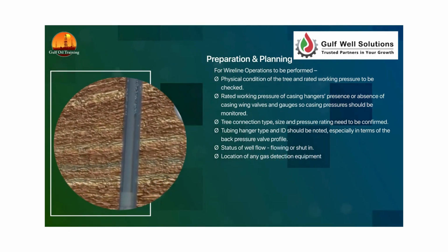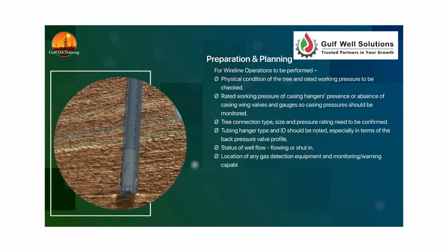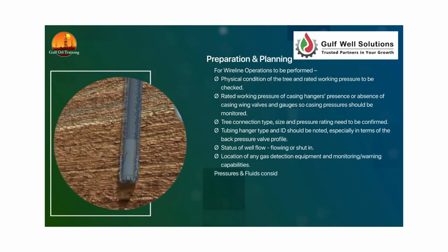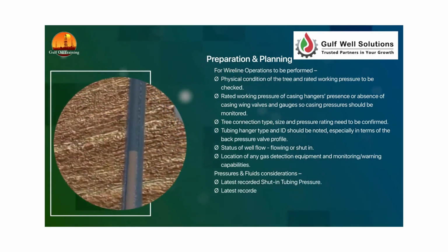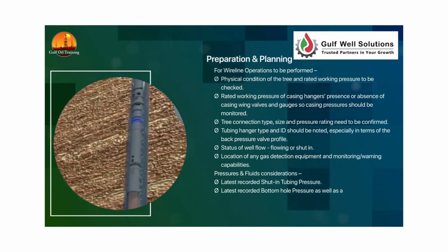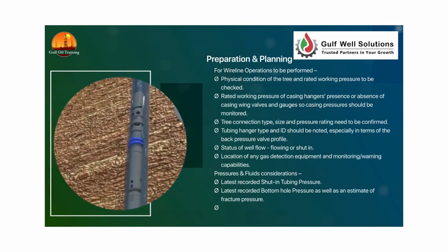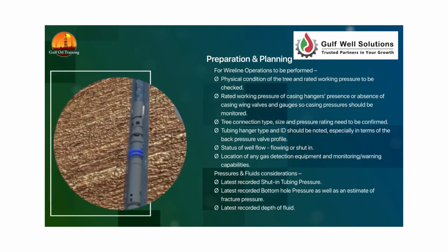Pressures and fluids considerations. Latest recorded shut-in tubing pressure. Latest recorded bottom hole pressure as well as an estimate of fracture pressure. Latest recorded depth of fluid. Types of fluids produced, sour or sweet, and if sour, the approximate concentration in ppm.